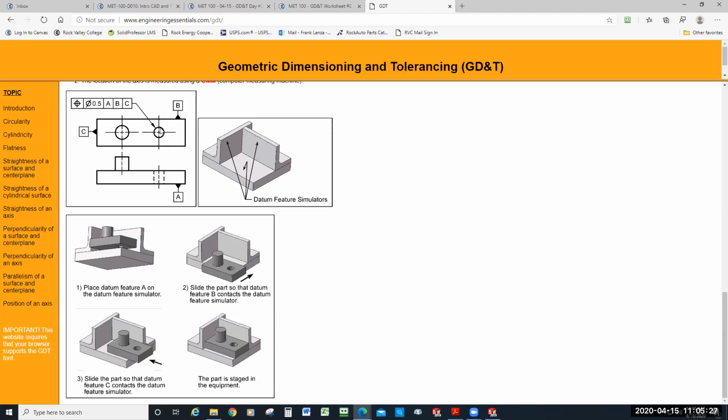It gets turned in the hole to try to cut away material. There's a reaction that's going to try to push back on it, and that's going to tend to flex the drill bit. I don't know about you, but I've drilled many holes where I thought I was drilling them perfectly straight, and when I look at the other side after it breaks through, it's not straight. Yeah, it's oblong down that end or whatever.